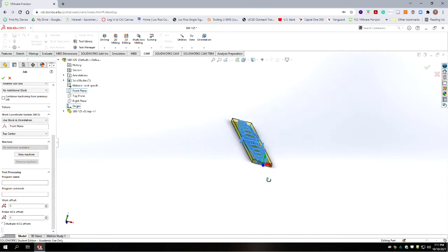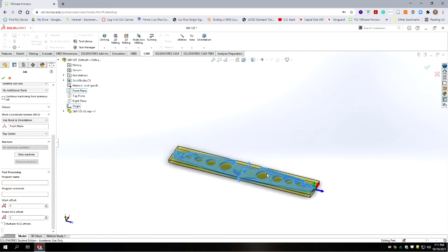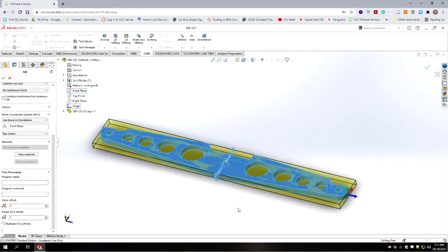So I'm going to rotate the model first to be in an orientation. It's still a 3D orientation, but where you would be viewing it, say, from the machine controller on the right, looking down at the table in an isometric. So what we see as the longest direction would be our x-axis. The short direction would be our y-axis, and straight up and down with the spindle orientation would be in Z. We want to readjust this origin to reflect that. So this is how we do it.